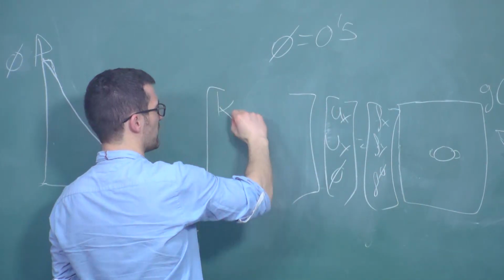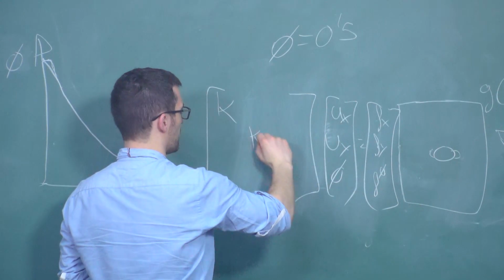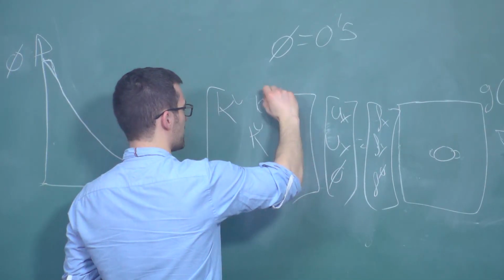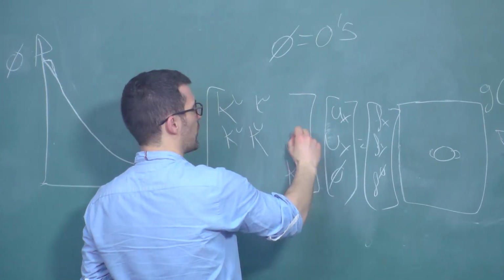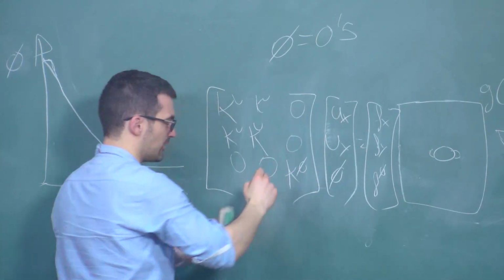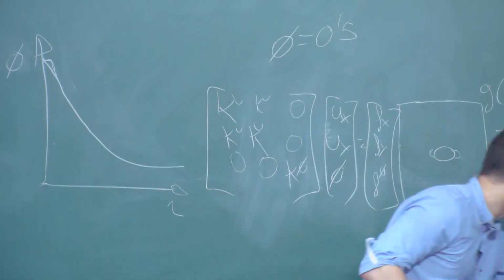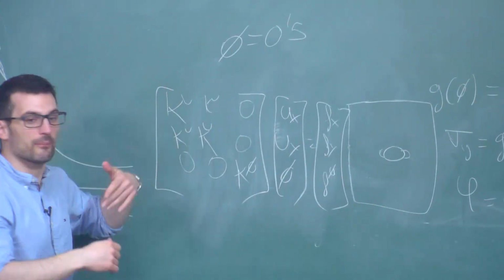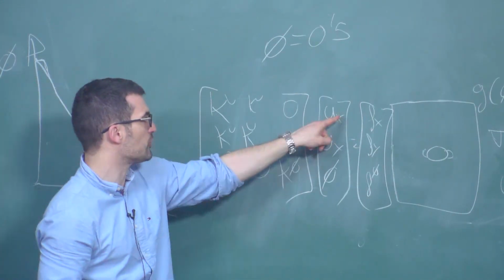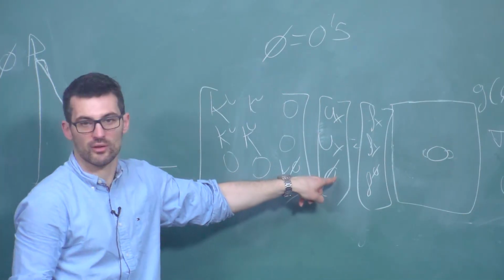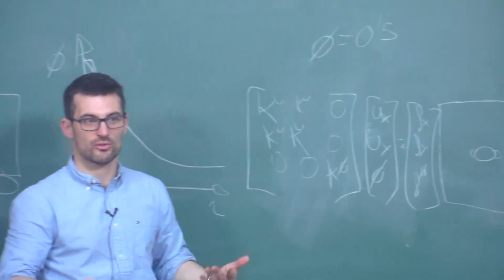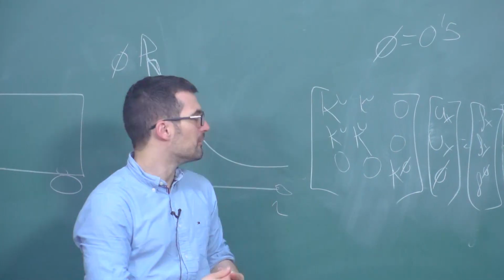And then you have here your stiffness matrix. I mean, it will just be all related to displacements. And then you have a phase field one. And what you do here is to be discussed later, whether you do coupling terms or not. But anyway, so you say, okay, normally when I do finite elements, I just solve for ux and uy. So now I need to do something else. I need to add an extra degree of freedom, like if I solve for temperature. So necessarily I'm going to have to define my own element.